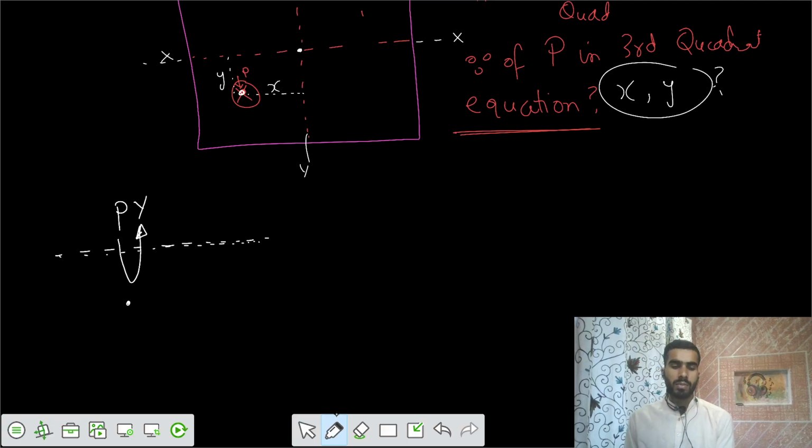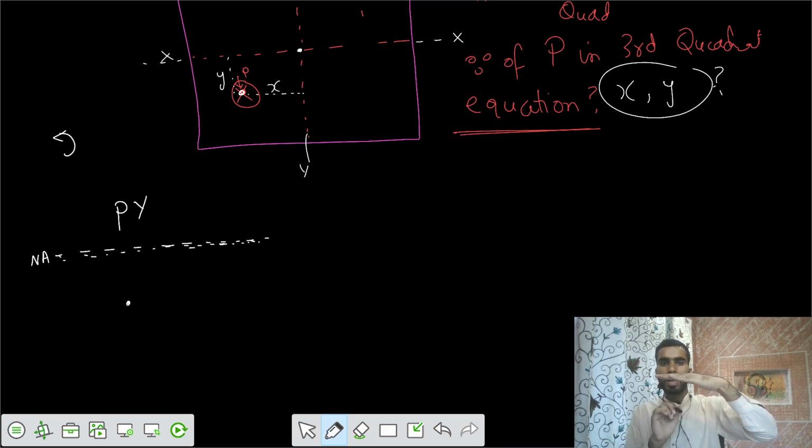So the neutral axis would be the x-axis for this moment. Actually, the direction of the moment is not in this way. Your load is below that reference x line, so the moment P into y is causing this moment in this fashion. So I would say anti-clockwise moment.